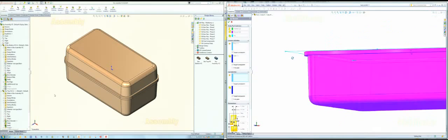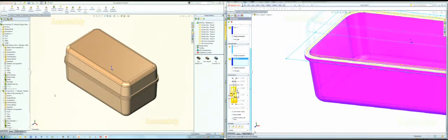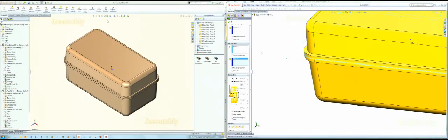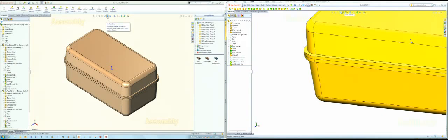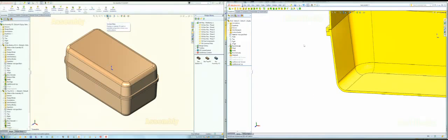Then the same thing for the bottom. This is where we want to put the lip, and we want to put it on that surface, and on the inside again. So it's going to build it all up. It remembers your dimensions from the last one, or you can save it as a favorite. It's remembering the correct numbers, so I'm just going to say OK, and it quickly adds a lip and a groove. And so now we're done.